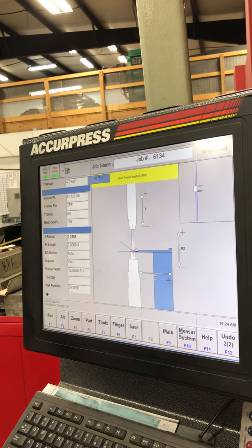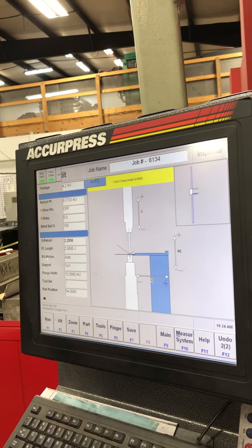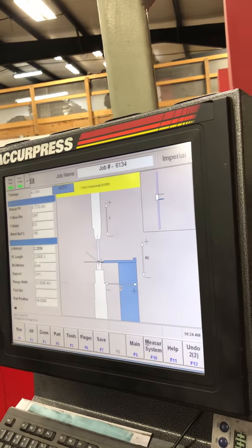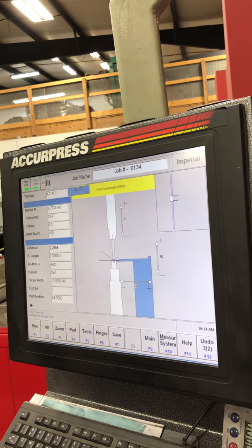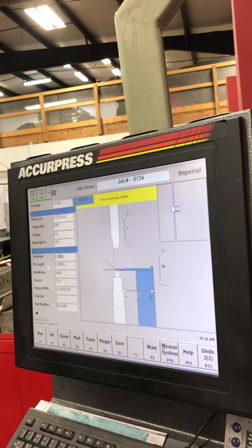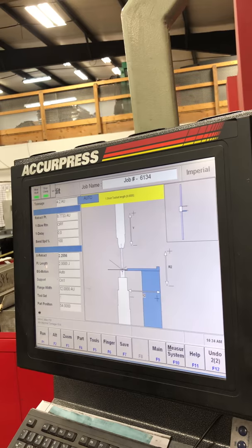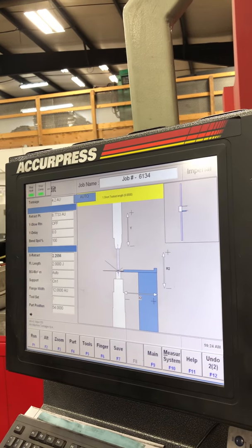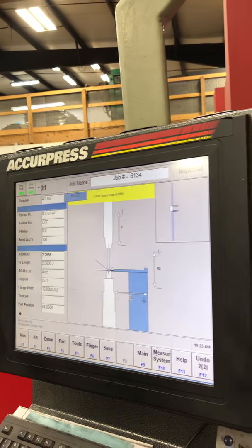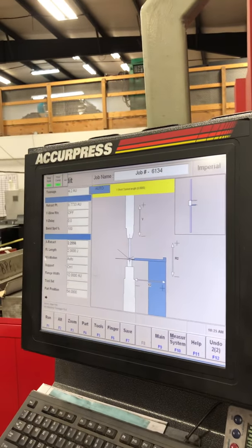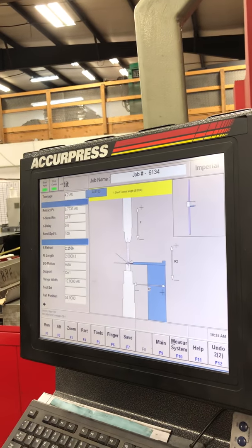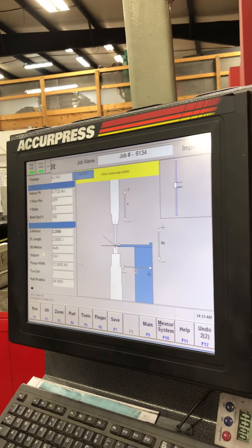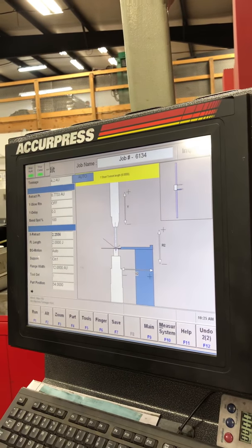86-degree dies, not bad, but when you're running acute dies and you're forming like a 30-degree bend, you've got to really watch out because it's going to push that tonnage down into that die where your normal tonnage, it's going to stall out maybe, but you juice up that tonnage. If it goes over where it needs to, you're going to split that die wide open. We've had it happen. We don't like seeing it because our tools are very expensive, but it does happen. So usually if you're going to really increase tonnage, back your angles off. Okay. Right? It's easier to put a part back in there and bump it again than it is to have it go over, damage a bunch of stuff, and it's too late now. You can't.